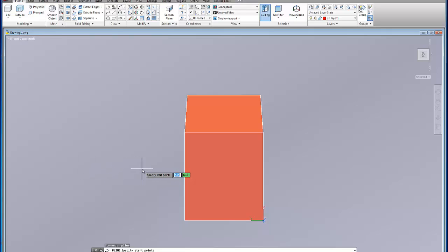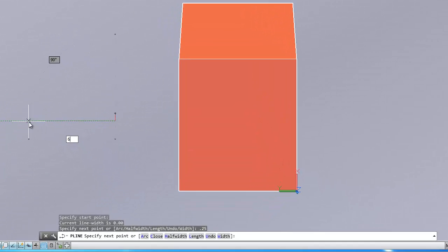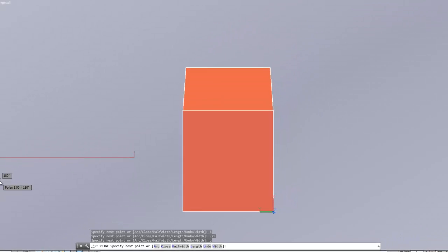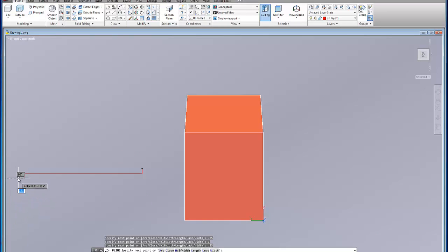And in this case I'm going to create the polyline, and we're going to start at the bottom of the hole. So I'm going to go ahead and make the hole 0.25 straight down, but we're going to make it 6 inches long. We're going to kick out the counter bore another 1/4 inch, and the, whoops, that was a bad angle. I want to make sure that we're straight up and down, 0.25, and then I want to go 0.375 vertical, and then I'll come back across and connect back to the original location.